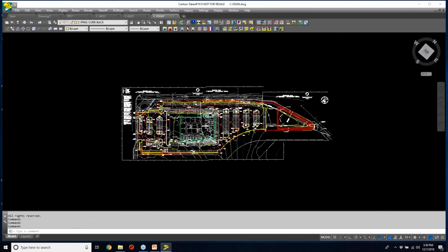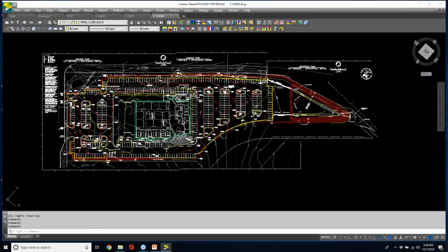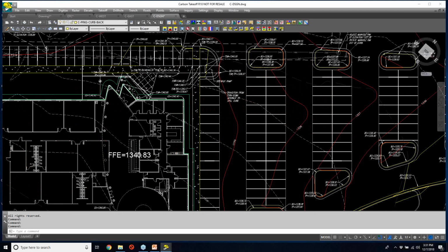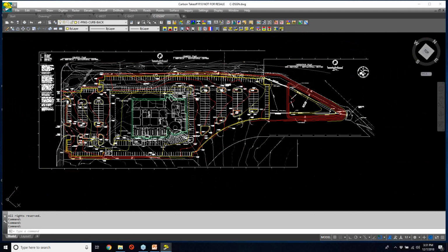So I've gone through in this particular example and brought in each of the three different sheets, and using the 2D align command, I aligned the building footprint using the coordinates that we had established, and that was the same from the coordinate geometry to the building from the base plan, and got them all aligned. Now, the one thing that I didn't talk about here today is that in this particular example drawing, I've actually utilized the elevate multiple in series command and re-elevated the design contours to the proper elevation for the sake of creating design surface models.